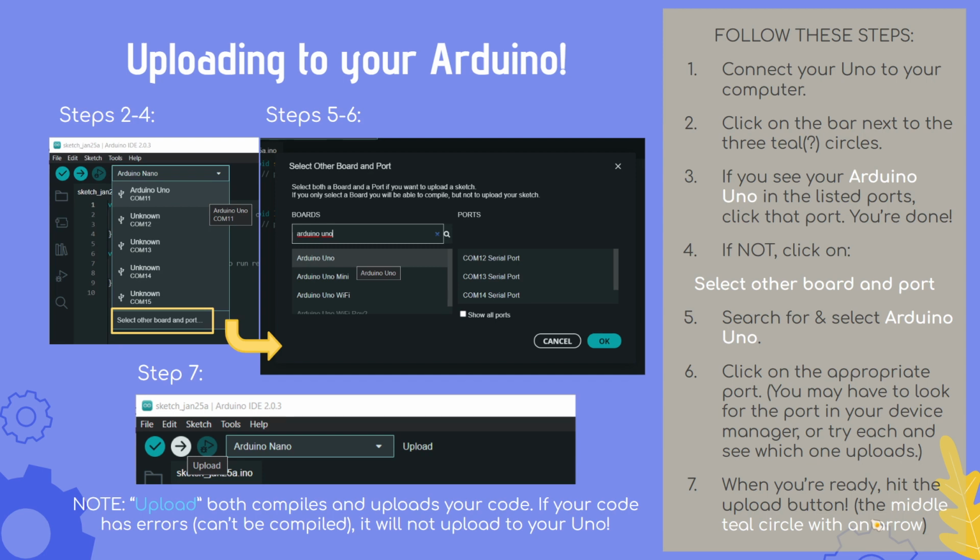Okay. Right, an Arduino. Right, and it should automatically connect to it. So ideally, it should be pretty easy for you to go into the drop-down menu and find where your Arduino Uno is, because your computer should recognize it. But if it doesn't, there is a little process that you can go through here to look for it. This isn't the 2.0 version though. In the 1.8 version, what you have to do is go to Tools, and in the drop-down, there should be a Boards thing that says Arduino Uno, and you should be able to select that. But if you aren't able to, please let me know, and I can get you there.